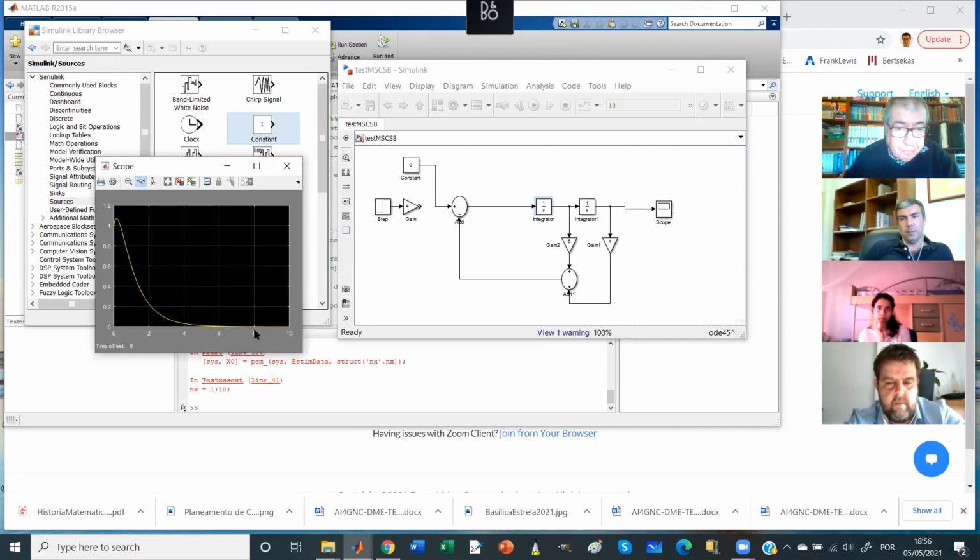So what is important here, there are many things that you are seeing here, but one main point is that position and velocity are the state. By feeding back the state, you can place the poles wherever you want. At least in this case, it was so.